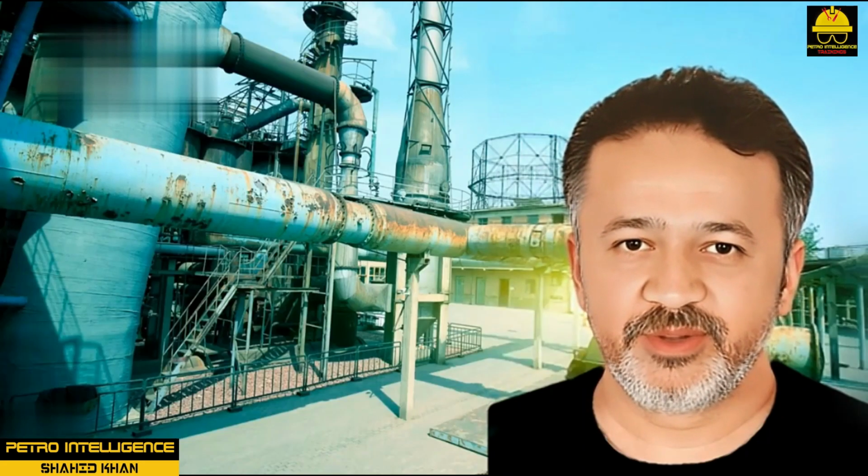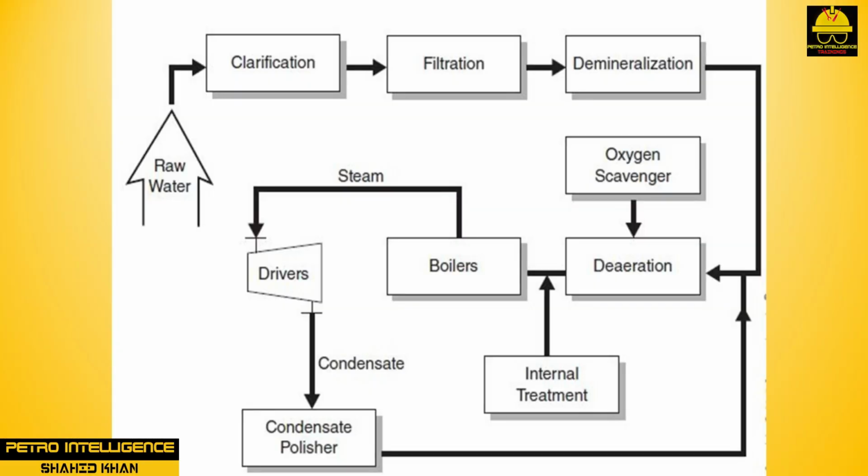Boiler feed water treatment. Boiler feed water treatment is the process by which suspended and dissolved solids are removed from the water used in a plant. Clean condensate and demineralized makeup water are deaerated in order to supply boiler feed water, BFW, to multiple BFW pumps. 2 or 3 pumps are used in the pump-around operation.